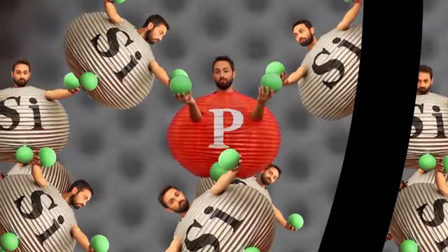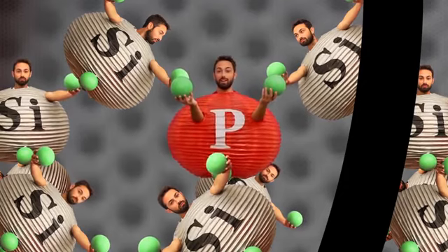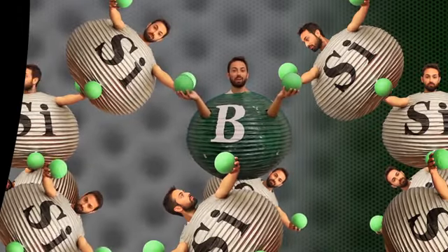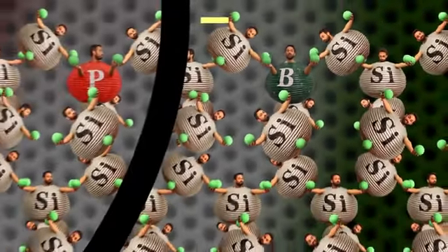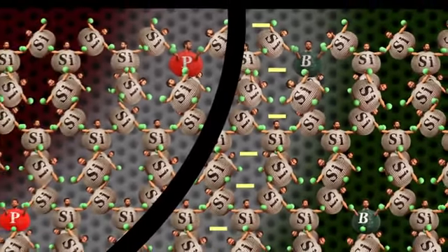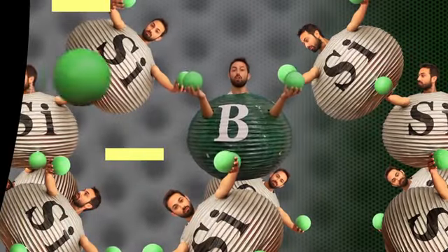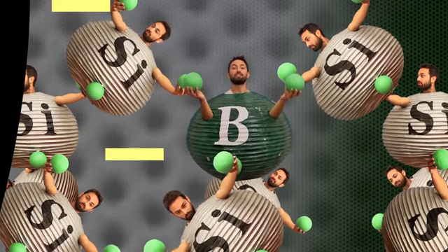What's been depleted? Charges that can move. There are no more free electrons in the N type. Why? Because they've filled the holes in the P type. Now this makes the P-type negative thanks to the added electrons. And this is important because the P-type will now repel any electrons that try to come across from the N-type. So the depletion layer actually acts as a barrier, preventing the flow of electric current through the transistor. So right now the transistor is off. It's like an open switch. It's in the 0 state.